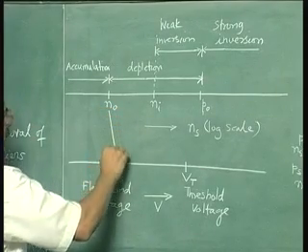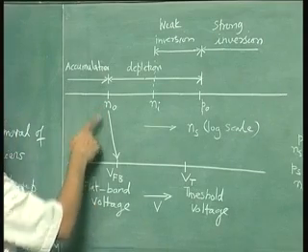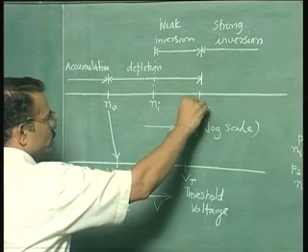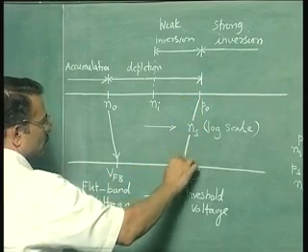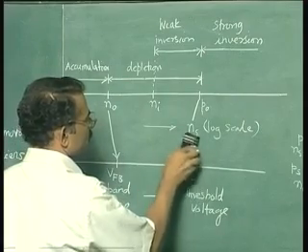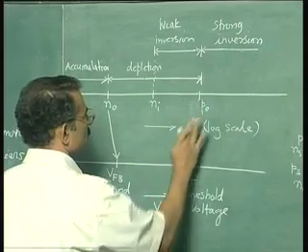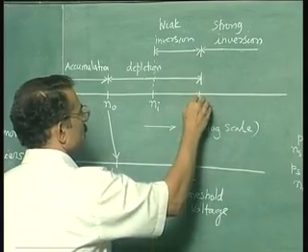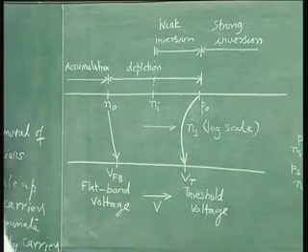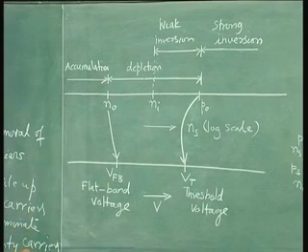So this translates to this point in terms of the voltage conditions in the device translating to terminal voltage, and this translates to the threshold voltage point. Let us understand why this point is called the flat band point.